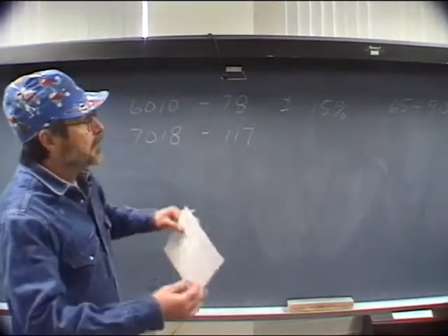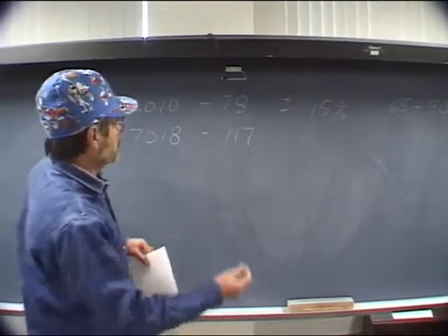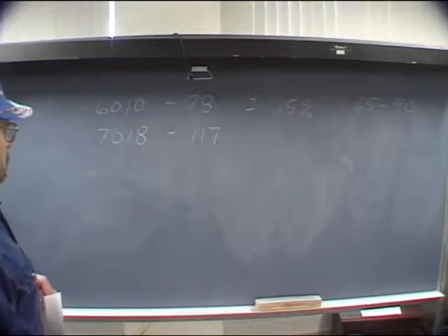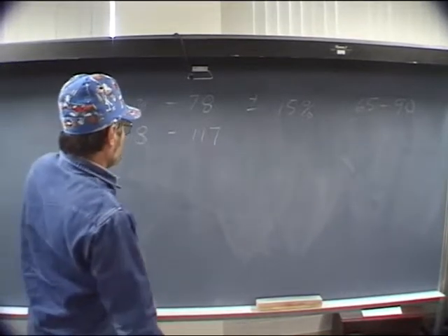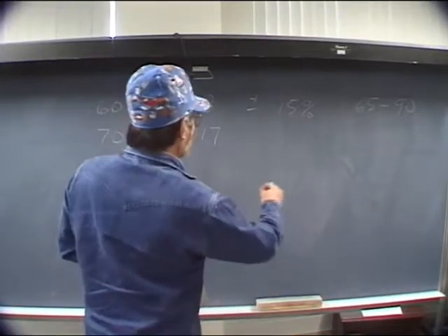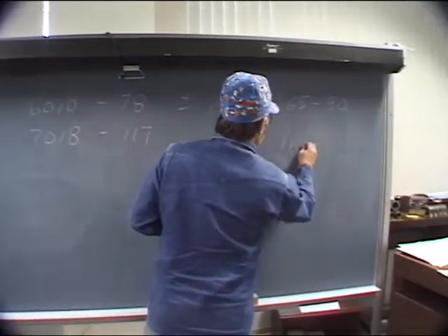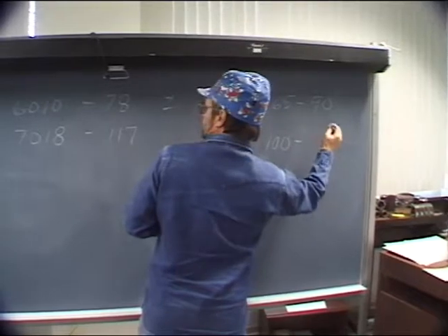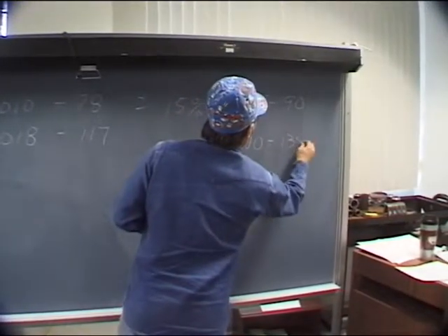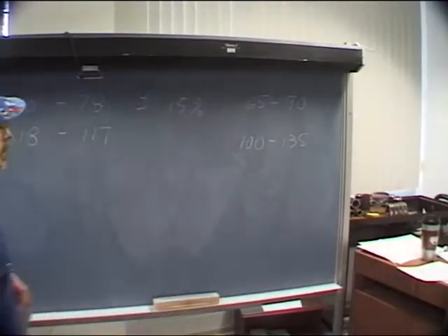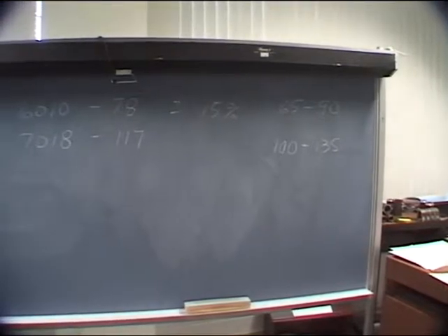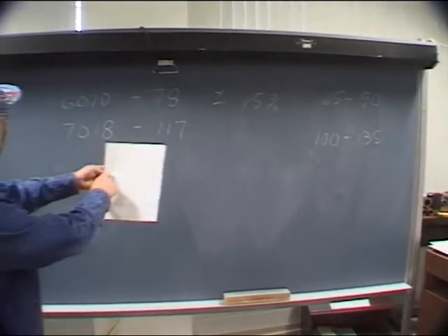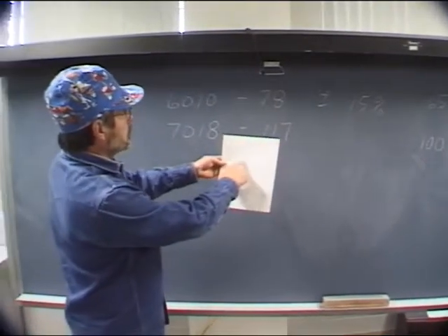So you've got to give them that leeway to work with. 117, let's see, that'll be about 17 amps. So we'll go down, our range here would be about 100 up to about 135, and that would be a good range for our 1/8 inch 7018. Okay, so within there we would put under amps, we would do our ranges.